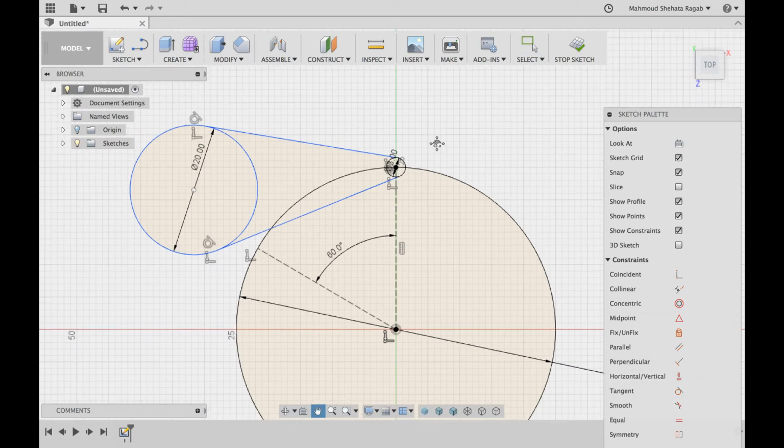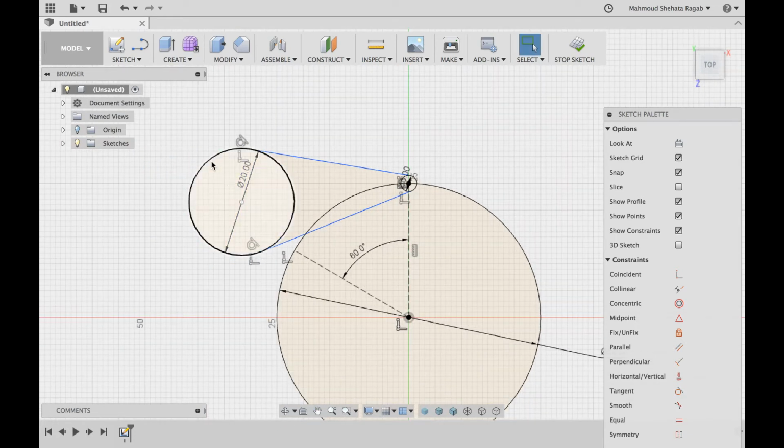Okay, now the way this is going to work, the drive wheel, like you saw in the animation, is going to rotate. Now when the drive wheel rotates, this pin is going to slide inside the slot and then somehow rotate and then go out from this slot, right? From this place where this slot is going to be, because the rotation is only 60 degrees.